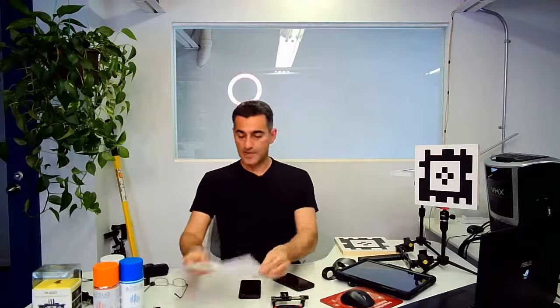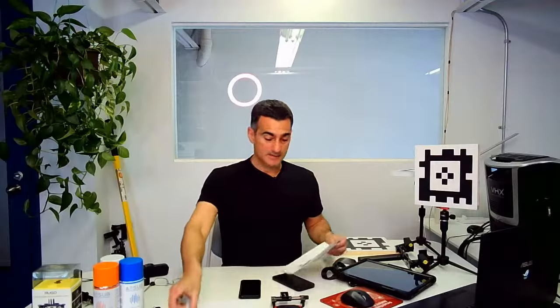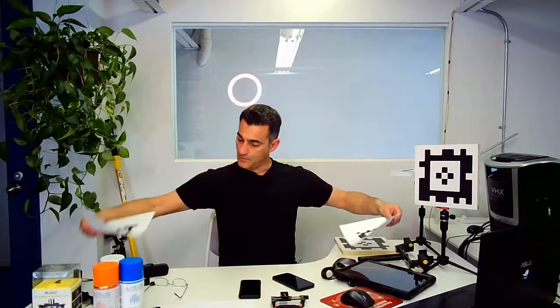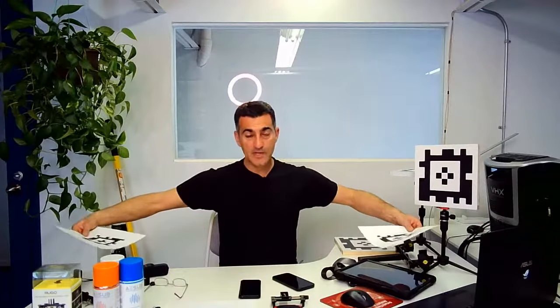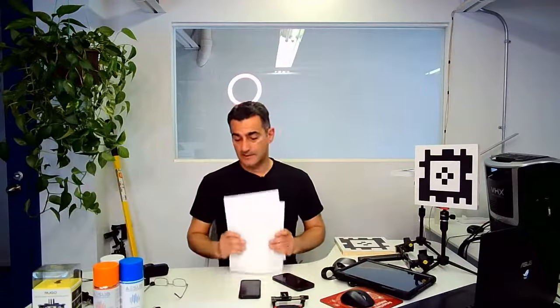The way the targets work is you're going to take two of these, and if I was scanning something here on the table, I would put one on the opposite end, spread far apart. The farther apart these are spread, and the more accurately you can still measure from center to center between the two, the more useful they are, and this will scale your whole project. Now, there are some other things that I'm doing with respect to the targets, and I'll show you a couple of things. These are completely prototypes.